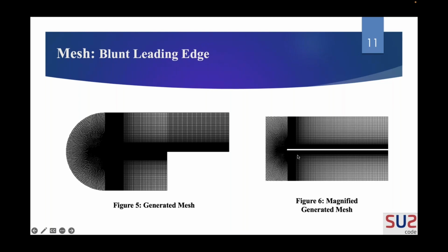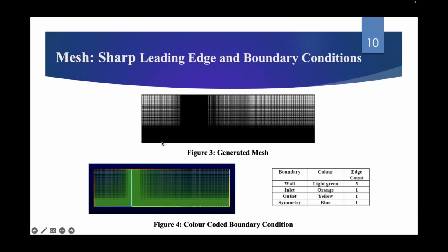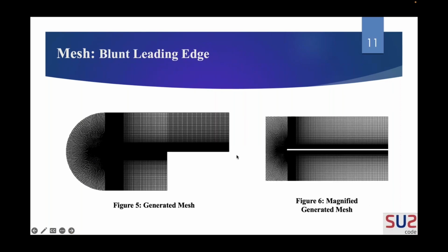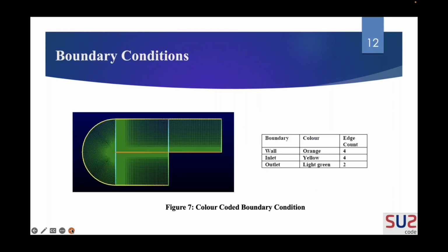The reason that we are focusing on this particular mesh is because we are only extracting the profiles perpendicular to the flat plate on top of it. So the bottom part does not really matter much. We're only focusing on the top layer. So this is the inlet. These two edges are the outlet, and this is the wall.